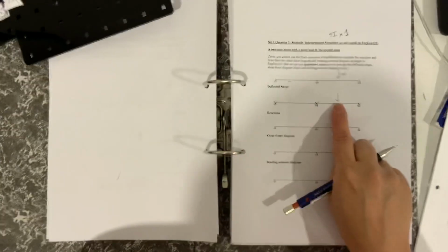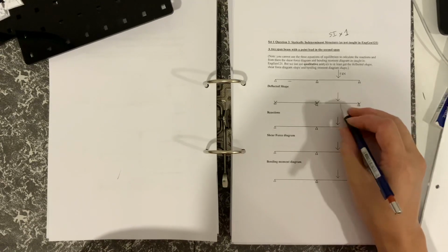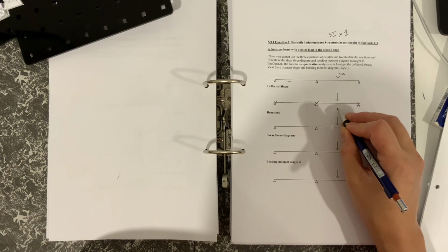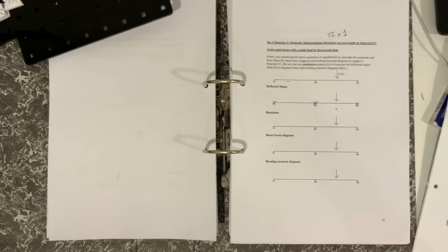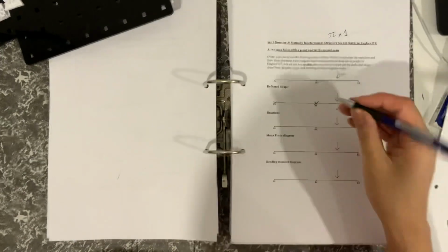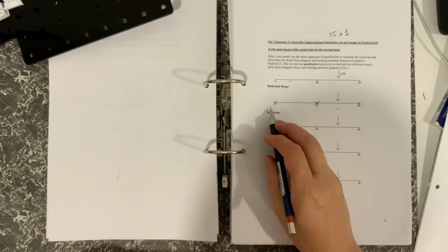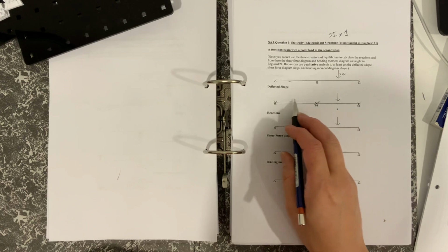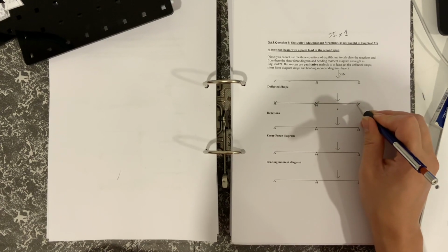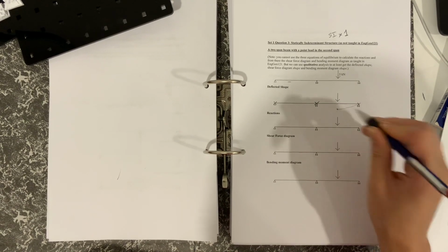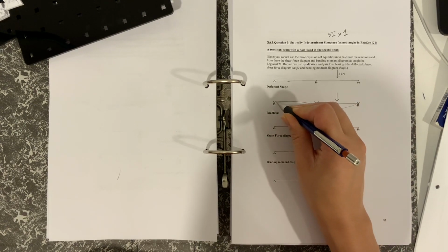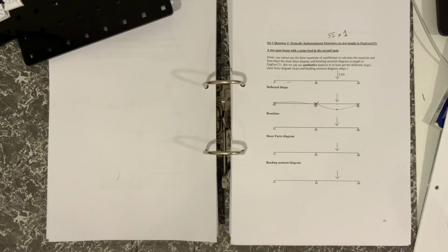And we would maybe be able to predict that the point where the load is being applied may be going down there with some deflection. And later on I'll show how you can calculate that deflection. So we would normally say the deflected shape plots a cubic. So I would just say try and draw a smooth line between those points that we know, and that would be your deflected shape.